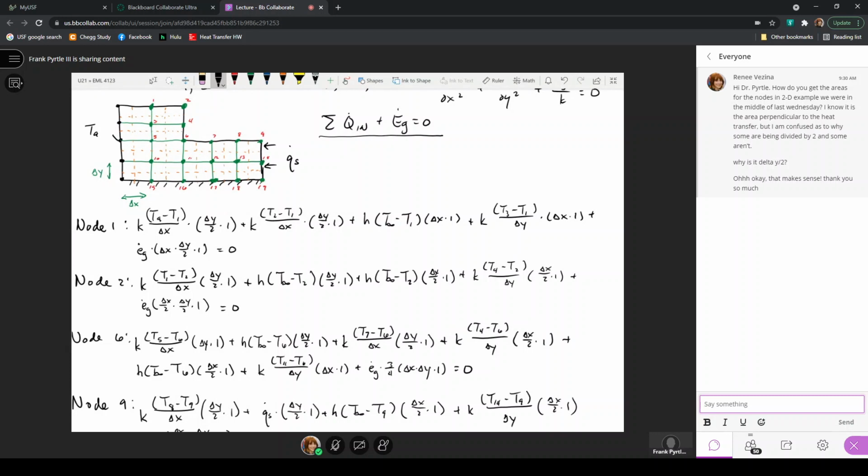But often once you calculated T1 through T19 and you visually represent them through colors or intensities of colors, or even if you're just looking at the magnitudes on a plot, on this plot, if we replace all of these numbers with the actual values of the temperatures that we would calculate from the node equations, then you can see, based on the generation and the boundary conditions that occur in this problem, you could at least qualitatively consider, do these temperatures make sense here?